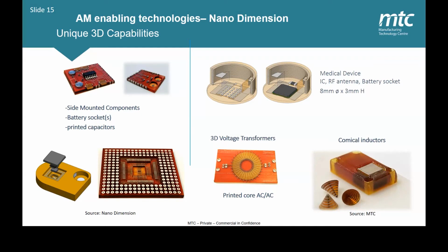The picture on the left illustrates that you can put side-mounted components, good for putting RFID tags and antennas all around the edge without the need for putting them at the top or the bottom side. The bottom left picture is like an MID style module where it can print three-dimensional. The IC socket enables integrating ICs within the PCB layers. This can be for reducing package size, saves real estate, and opens a path to miniaturization of products.